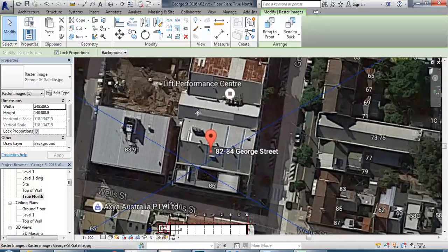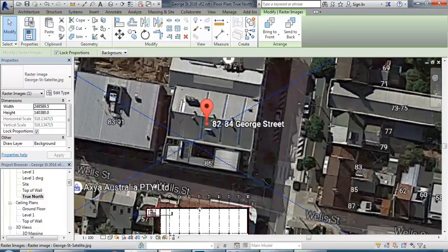And then I need to rotate this image to line up with my building. You'd never want to do it the other way. So you'd never rotate your building, hopefully. Anyway, that's the way you're thinking. Don't rotate your building to line up with north. Some people will tell you your drawings should always face towards true north, but that is definitely not the case with design drawings.